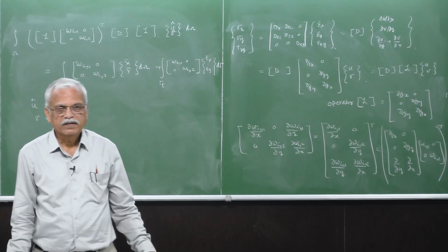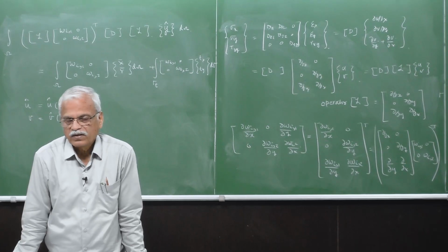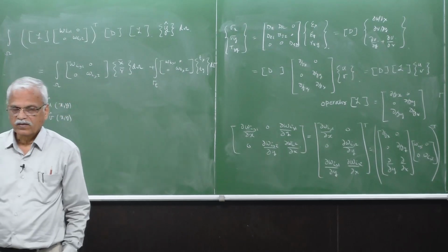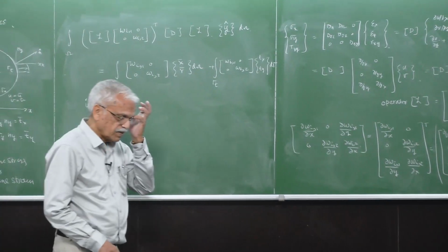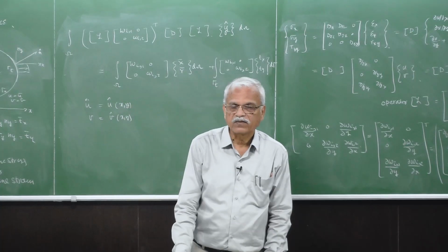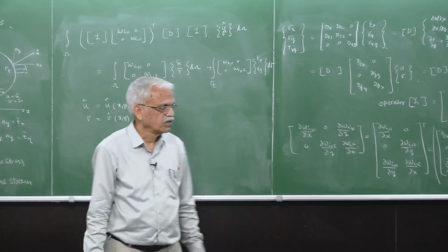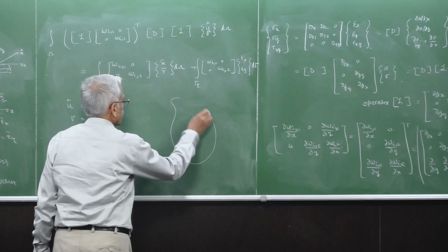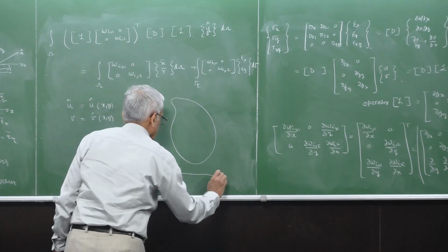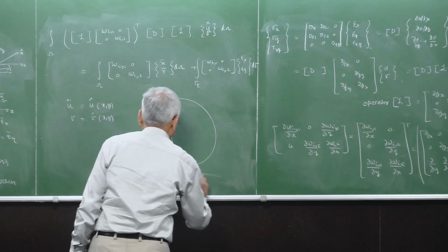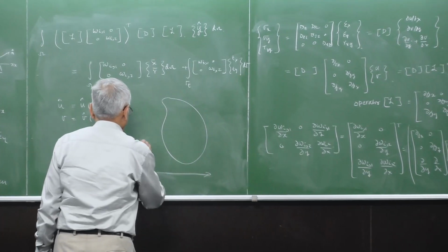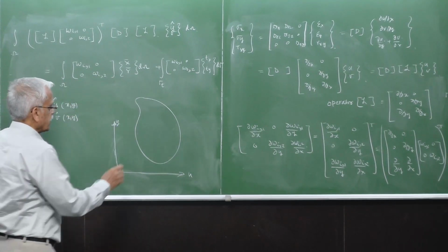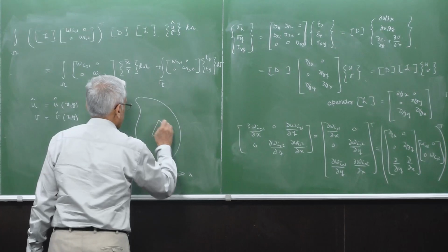On the other hand, if they have any discontinuity, which will be at the element boundaries, it has to be a finite discontinuity. The derivative has a finite discontinuity, which means that the function is a continuous function, so C0 continuous. Okay, so this is in 2 dimensions. So in 2 dimensions, the one which we take is the triangular element.